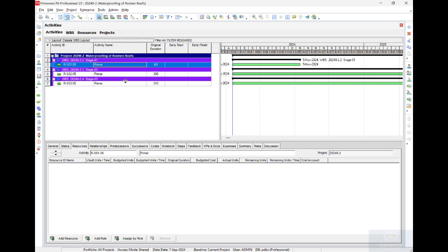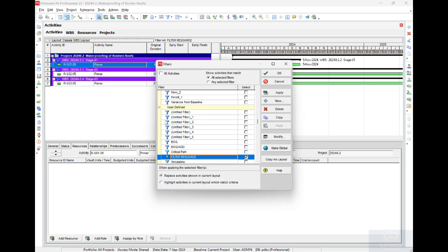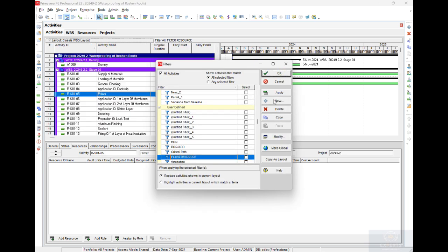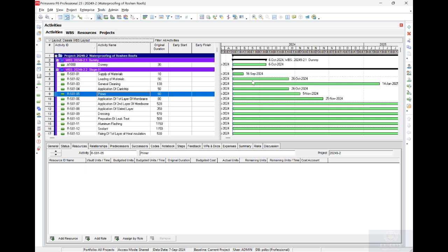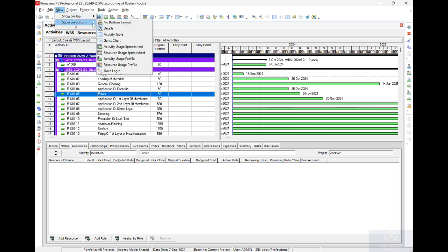After that, by using the tools of Primavera like global change, you will make the assigning. After you make the assigning for the resources, you can start building the logic relationships and check all this. So you have relations, you have durations, and you have resource loaded. You can check from view the resource allocation and check that there is no over-allocation. It will be good, so you can submit your schedule for discussion with your managers and your construction team.